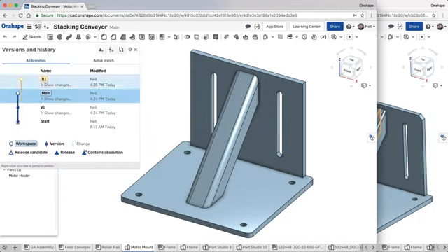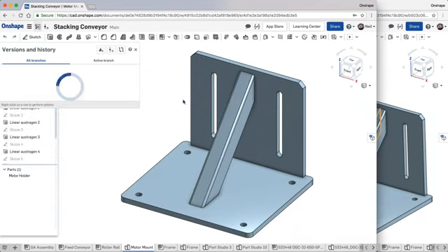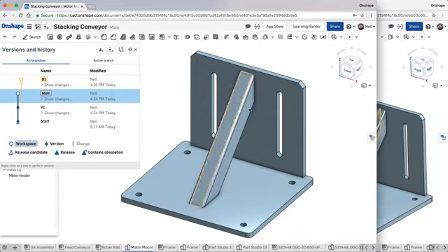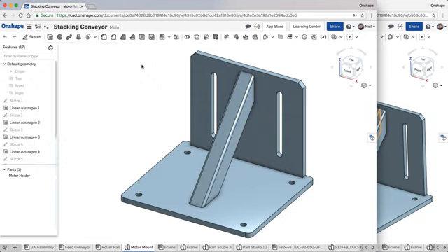This is very easily done by merging that data into this current design. You'll see within a couple of seconds you've now got the smaller fillets, the thinner beam, the chamfers added to the corners. So it's a nice, easy way to manage multiple design scenarios without having to do an entire save as copy, which you would have to do with old CAD using files, which gets very messy very quickly.